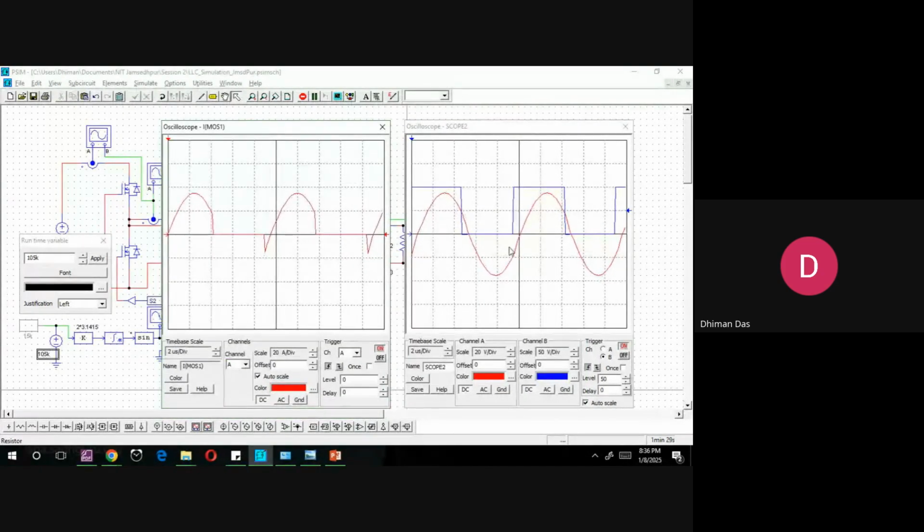Okay. Now you can see this is the current waveform of the tank. You can see the cycle is not yet completed. It starts here along with the magnetizing current. It is not completed yet, but again you are pushing the opposite side of the oscillation. So that is why it is in buck mode, or you can say inductive mode.